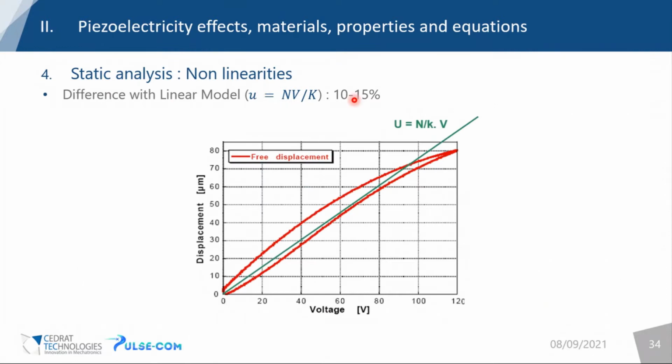But in the real world, it's not totally linear. I've shown here linear curves, but it's not like that in the real world because you have the parasitic effects I mentioned before, so pyroelectric effect, electrostriction, etc., which means that you don't have a linear relation between the voltage that you apply at the edge of your piezo ceramics and the displacement or the deformation of the ceramic.